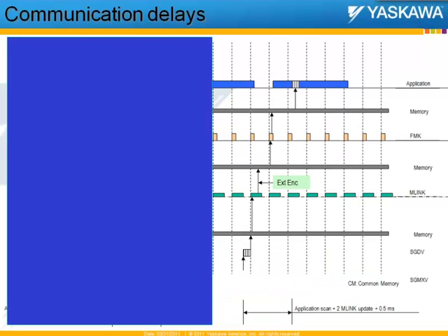Moving on to the second of the parameters that I wanted to talk to you about. The second involves communication delays. Now, any network or any motion system that involves communication or a network that's used for communication has some kind of a communication delay built into it. And what you see on the x-axis, the units on the x-axis are Mechatrolink updates, or the updates that the controller uses to send data or commands into the servo pack, and the same updates are used to get updates from the servo pack into the controller.